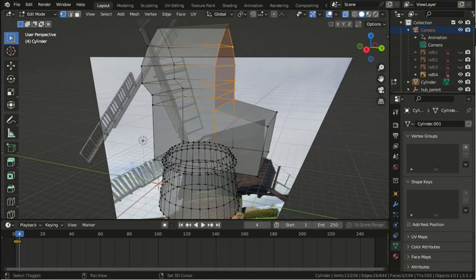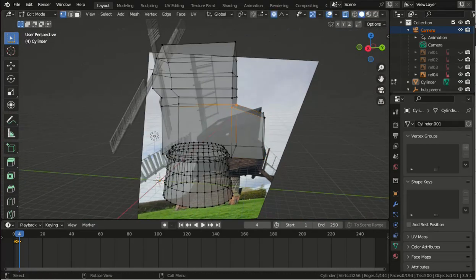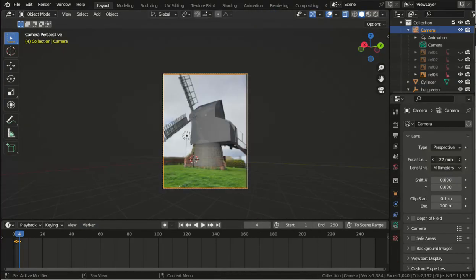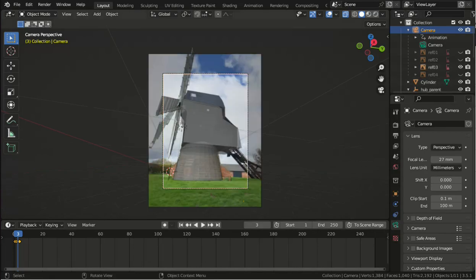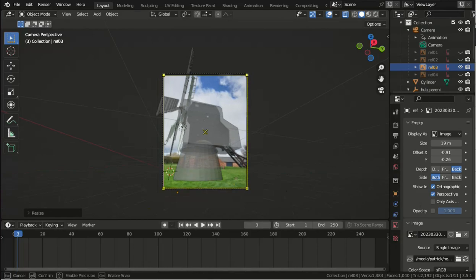Finally, I've come to the conclusion, actually I googled, but I could have come to the conclusion through this process, that the focal length equivalent for a 35mm sensor is 27mm. So finally, making the focal length 27, I now move the camera. And notice, after I've moved the camera with the walk navigation, I then go and check the Z position to move it 1.5 metres above the ground, which was about the height that I would have been holding the camera.